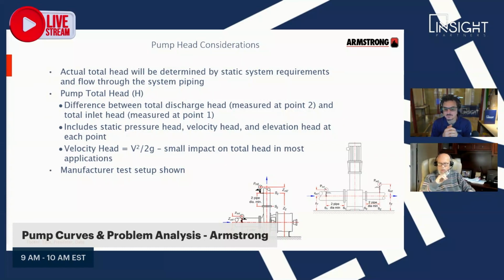Okay. So when we look at a test rig, the pictures that I've got up on the screen are a HI test rig setup. We build pumps to the Hydraulics Institute standards. We have to, just like every other pump manufacturer. When we look at this, this is how we set up, and this is the way we test. Understand that when I'm doing my test setups, I want to be 2 pipe diameters away from the pump on the suction and discharge side.